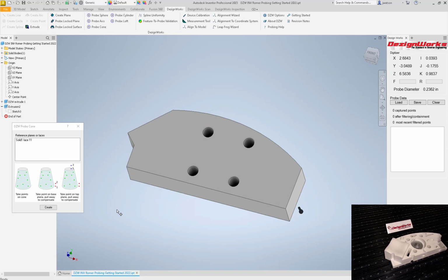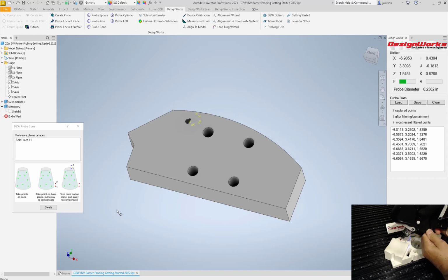So we're going to take the roller arm, come over here. We're going to take some points. The order doesn't matter. Just make sure you try to get 360 degrees to get a best fit. Okay. Now, like the instruction says, where's the bottom? Hold the probe at the bottom of this. Tap the trigger. Pull up a little bit. Don't pull past the height. You'll confuse it. So we define the bottom. Pull up, half the distance. Tap the button. Define the top.